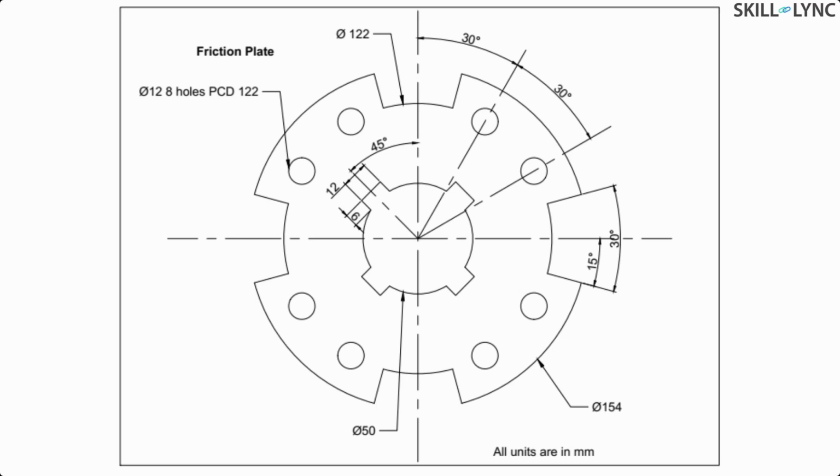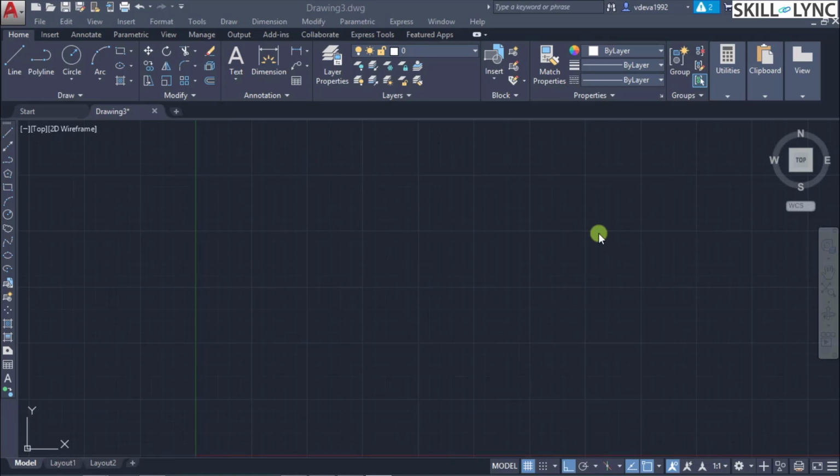Always please take note of the units again. All the units here are mm. Then again, note what dimension space you are working in, what the maximum dimension is, and check whether your limits are all okay. Then look for key dimensions that will help you to construct the drawing, and finally the application where it is going to be used. So now we'll start the drawing.